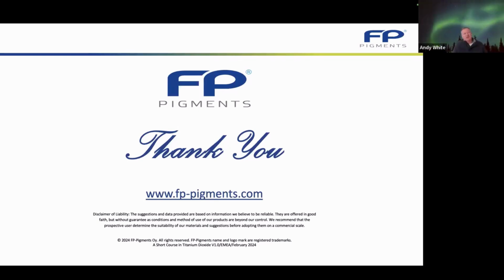I think in all fairness, most people formulate paints on an evolutionary basis. So they will take the formulation they have and they will change something. Okay. And essentially the acid test, if you want to see if you have something like flocculation, is the opacity up or down? Has the color changed a little bit? Because you get a little bit of metamerism, it'll be ever so slightly redder if you've got proper flocculation. But you'll see a big difference in opacity.